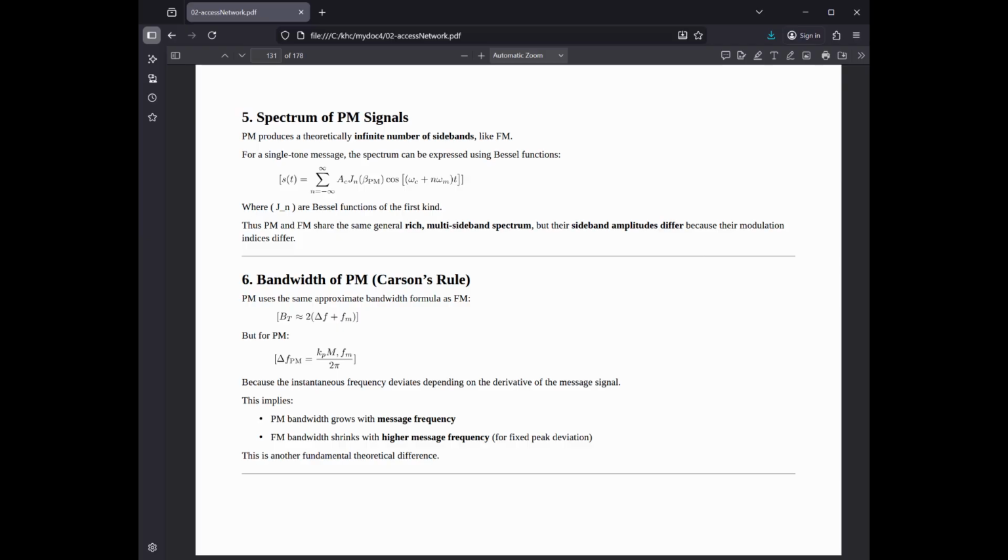The modulation index determines how much space the signal takes up in the air. In narrowband PM, the signal is very thin and looks similar to an AM signal spectrum, with only 2 major sidebands. In wideband PM, the signal produces many sidebands. The number of active sidebands is determined by Bessel functions. As β increases, more power moves from the center carrier frequency into the sidebands.